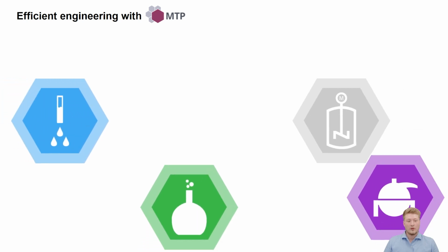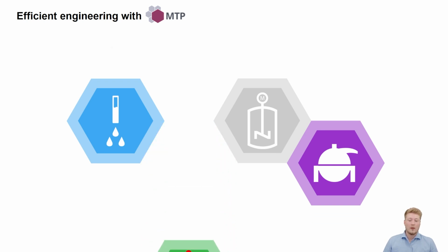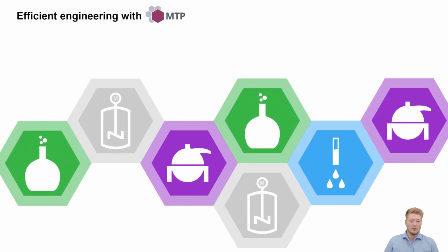The MTP concept really focuses on dedicated modules. So you think in, for example, a reactor module, a mixing module, or a dosing module. And these predefined and pre-developed modules you can easily then put together for a short time to market. Each module then communicates with a higher process orchestration layer implemented in, for example, a SCADA or DCS. Another advantage is that you gain a quick time to repair by just replacing single modules if there should occur a failure. Or, of course, gain a high flexibility because you can just rearrange the modules, add or remove some modules to create a whole new process.